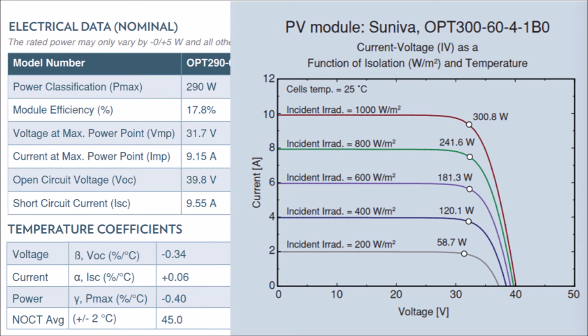Bring us back to our temperature coefficient discussion. The temperature coefficient of power is a negative 0.4% per degree Celsius. So at a surface temperature of 50 degrees Celsius, there is a 25 degree difference between that and the standard test condition. So a 25 degree temperature differential multiplied by 0.4% correction factor means a 10% loss of power due to temperature alone on this moderately hot summer day.